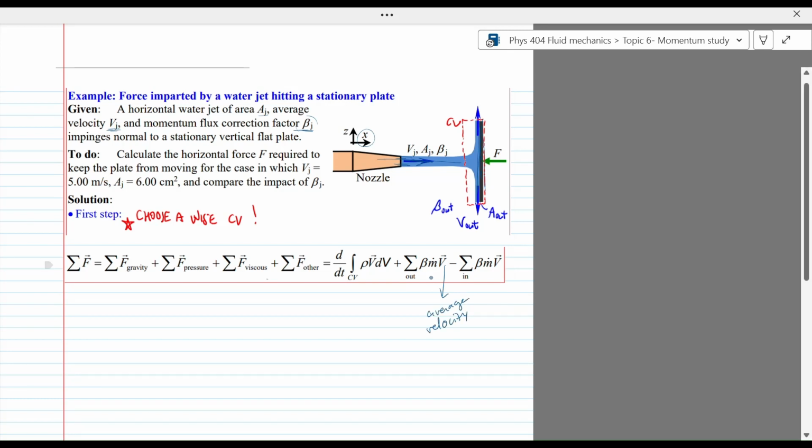across any inlet or outlet, but because I know that my velocity is not really constant, taking its average will make a big approximation. You can see here that across any outlet I actually have something more like this, where I have some velocity profile, and taking the average of this profile will actually just lower the precision of my answers. So we use this correction factor beta, in which we account for the non-uniformity in my velocity.